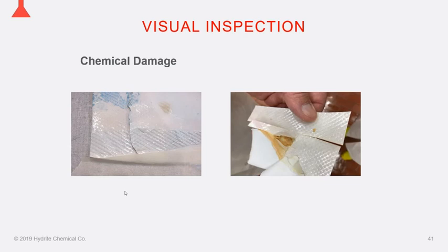So a membrane that doesn't have much flexibility when you pull it out, cut it open, and start bending it. You'll either see this as cracks immediately or over time. There's actually a test that's been developed by several manufacturers that essentially determines the number of folds that you can give a piece of membrane before it starts permeating a dye.